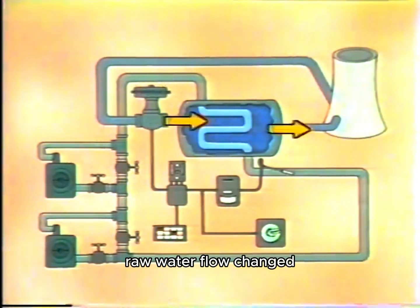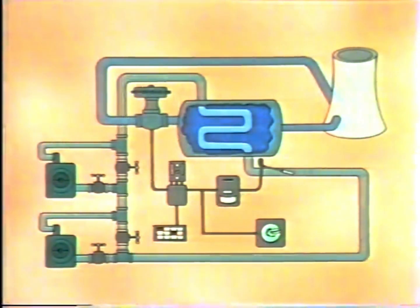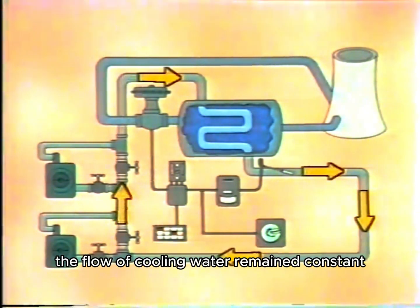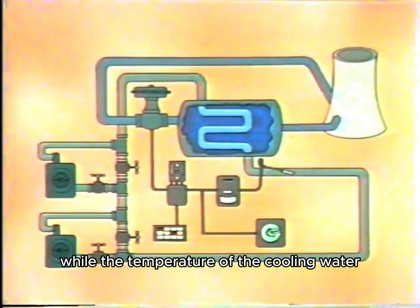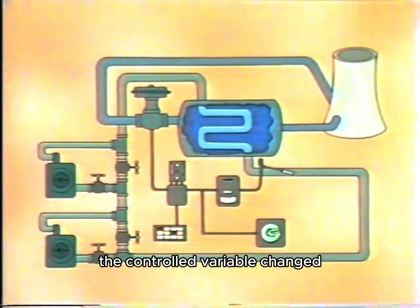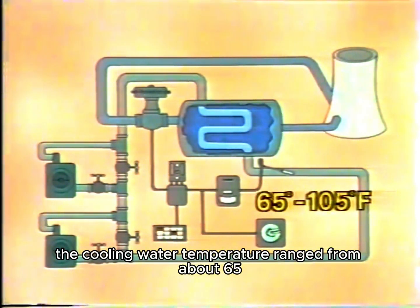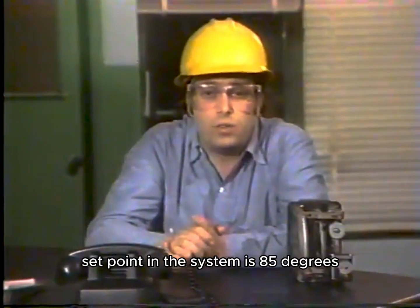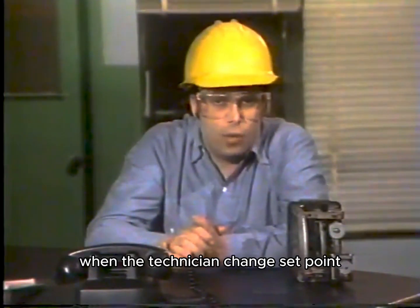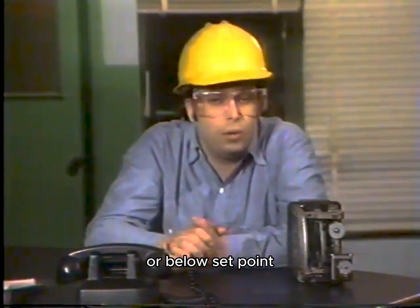Raw water flow changed depending on the signals that were sent to the actuator valve assembly. On the other hand, the flow of cooling water remained constant, while the temperature of the cooling water, the controlled variable, changed. The cooling water temperature ranged from about 65 to 105 degrees Fahrenheit. Set point in the system is 85 degrees. When the technician changed set point to create load changes, the cooling water temperature did not vary more than 10 to 20 degrees above or below set point.